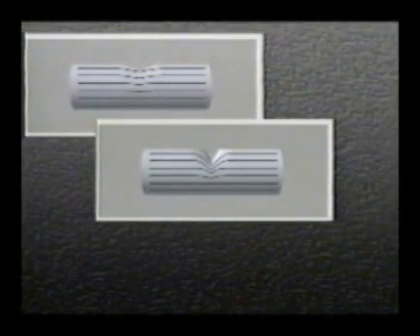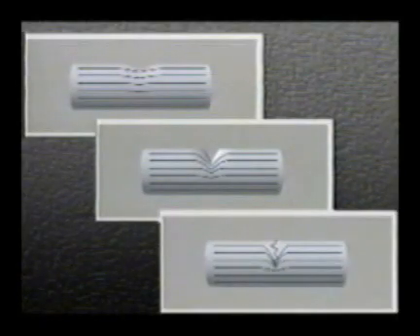The amount of stress increase that occurs depends on the sharpness of the stress raiser. Gradual contour changes increase stress slightly, while abrupt contour changes increase stress significantly. A crack has the sharpest, most abrupt contour change possible, making it the most severe stress raiser.